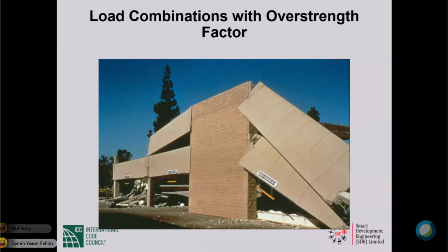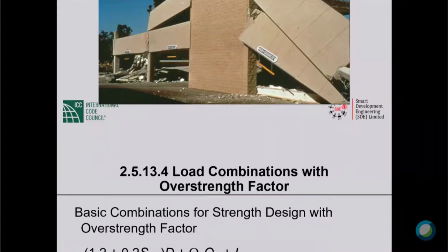Okay. So that was the lesson that was learned, that the collectors have to be stronger than the shear walls to which the collector forces have to be transferred. So that's what led to the requirement that collector elements of diaphragm shall be designed using load combinations with overstrength factor.